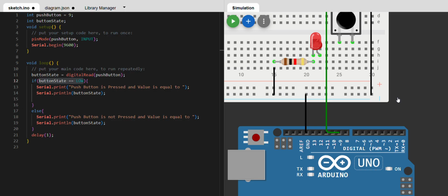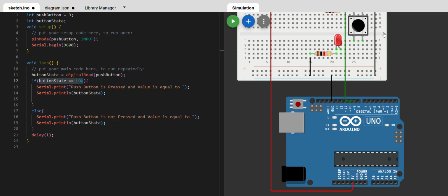In the first video I discussed the breadboard, right? These horizontal dots are shorted in the case of plus and minus, whereas in the case of A B C D E, F G H I, these five vertical dots are connected like this.